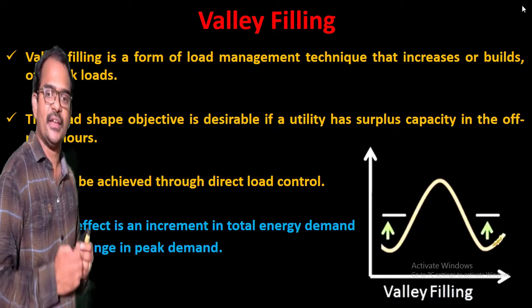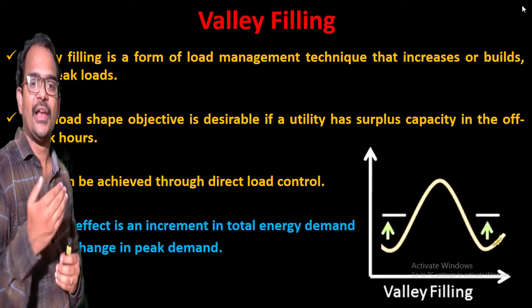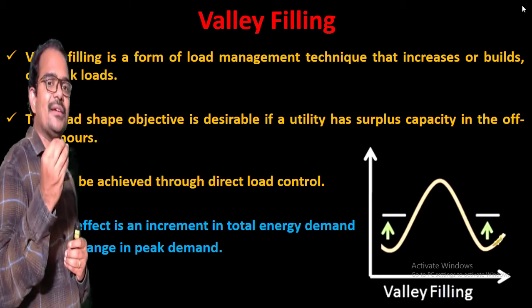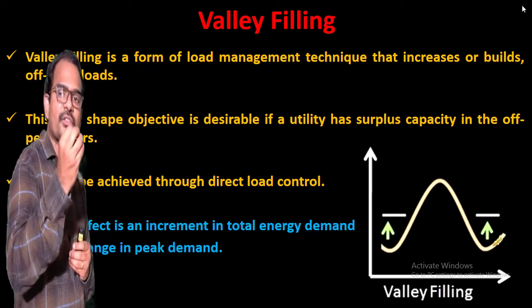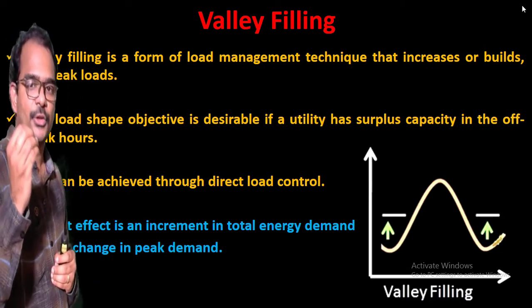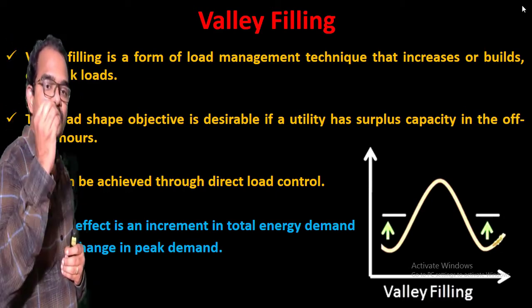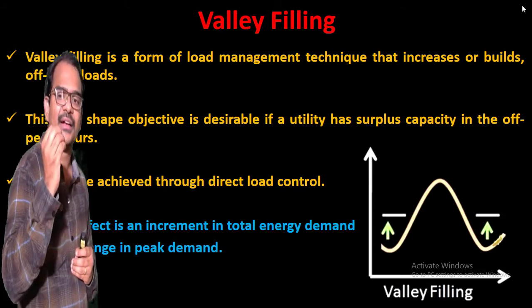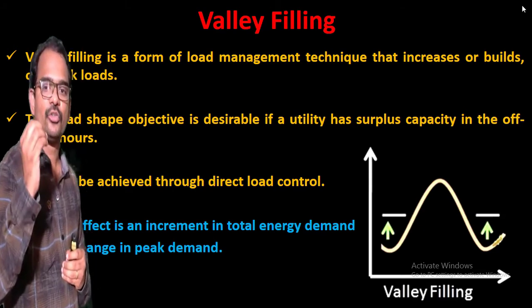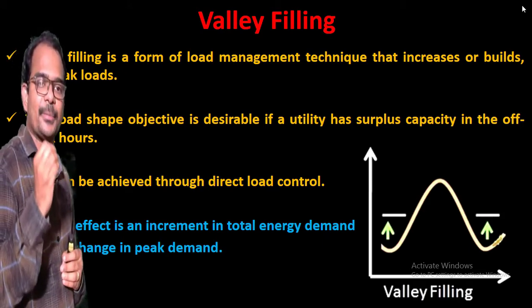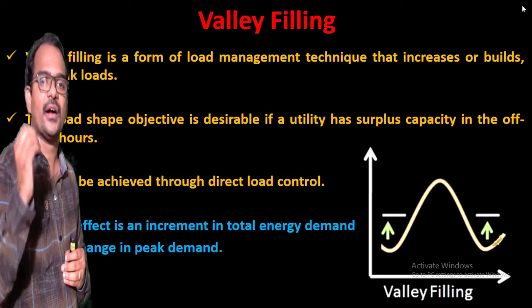And the fourth technique is valley filling. What is this valley filling? Valley filling is a form of load management technique that increases or builds off-peak loads. That is, the load shape objective is desirable if the utility has surplus capacity in the off-peak hours. So this valley filling load shape objective is desirable if the utility has a surplus capacity in the off-peak hours.